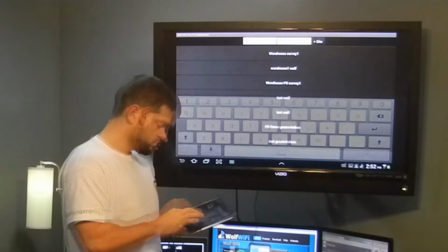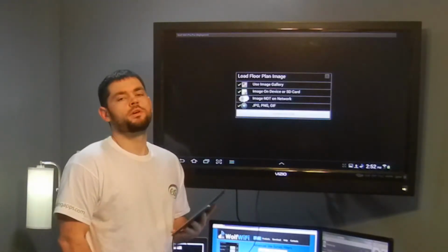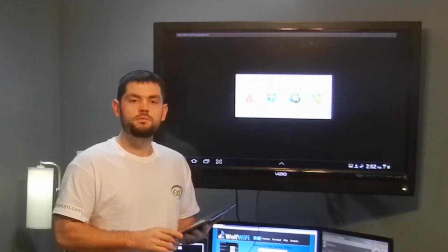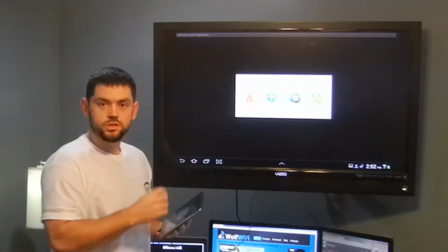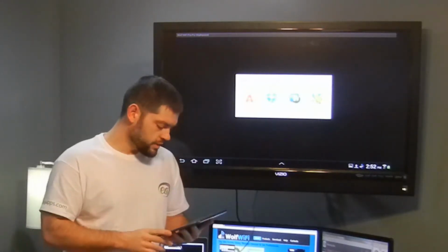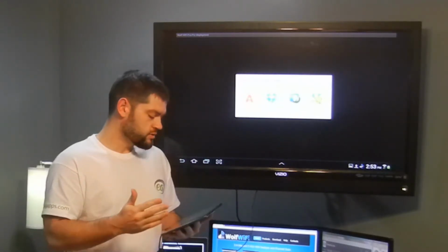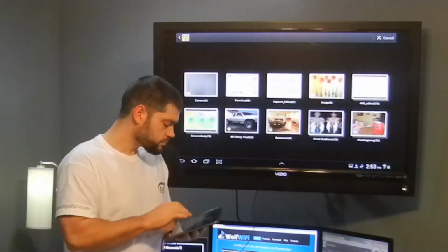it. Tap on it and select Manage. You're going to get that familiar screen. If you've used the survey tools before, you need to load a floor plan. As we've talked about in other videos, you need to use the gallery to pick your floor plan. That'll give you the most consistent results. Some of the other tools out there today, file manager tools and image manager tools, you have some mixed results with those. So if you stick with the built-in gallery, you'll be good to go.